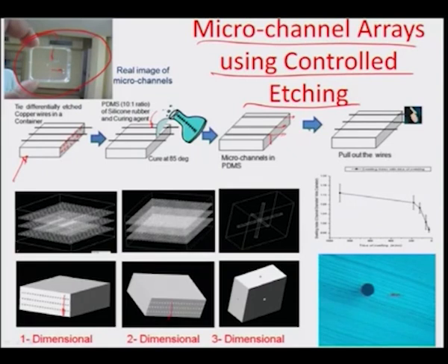So, the only issue which comes here is in terms of swelling the PDMS matrix and shrinking it back, and we have seen that while doing it, the circularity of such a channel is very well retained, and you use a solvent to typically expand this PDMS, and then if you evaporate it, the solvent goes away, and it de-swells back, and while de-swelling, it maintains the aspect ratio of the structures and features.